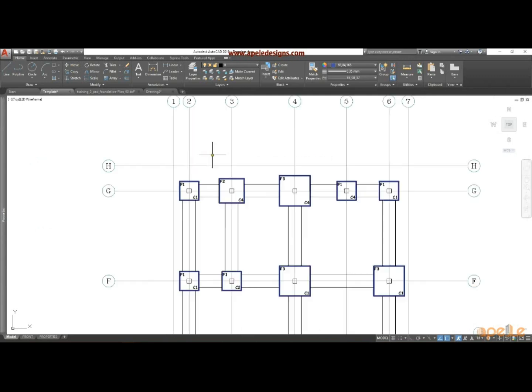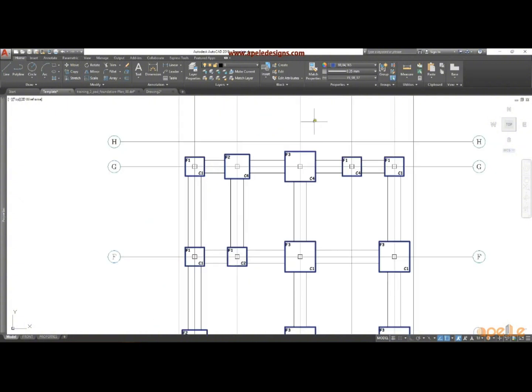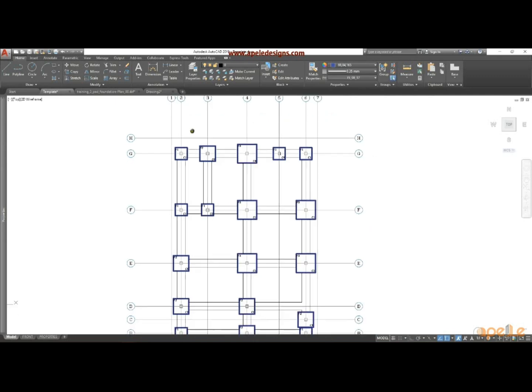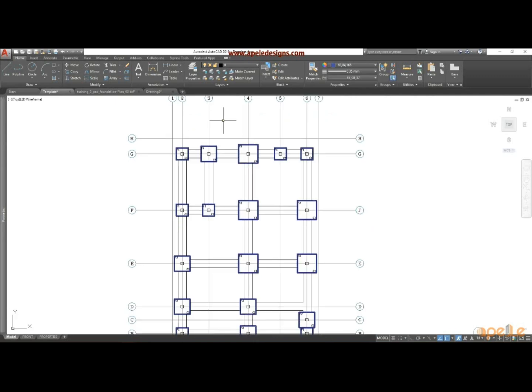Okay, this is good. Now you notice I make these dotted lines and it's not visible. I'm going to adjust my L2 scale. To adjust your L2 scale, just type L2 scale on your keyboard. Hit enter. Let me increase the value to maybe 100. Nothing changes. I'll hit enter again. Increase the value to 1000. Now this is perfect.